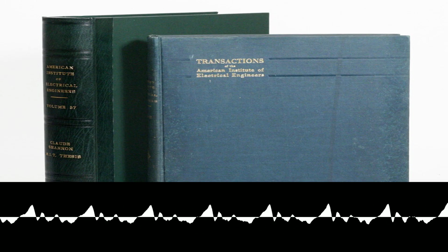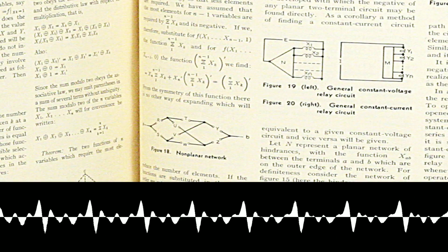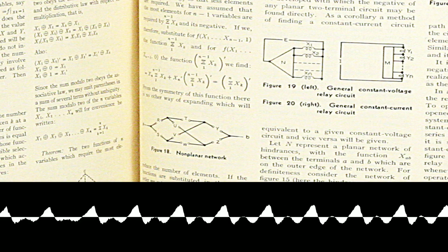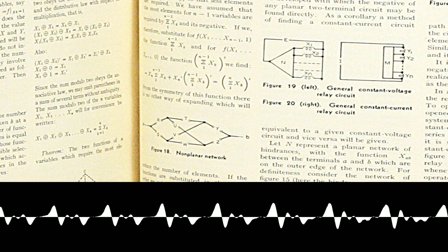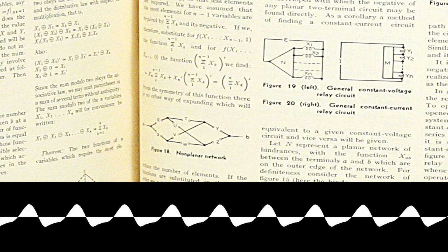Section 6: Minimization Theorems and Simplification Techniques. Shannon delves deeper into circuit complexity by illustrating and proving several theorems that can simplify logical expressions. A significant contribution towards efficient circuit design, a foundational theorem, is the absorption law, which asserts that expressions involving redundant circuit elements can be simplified.